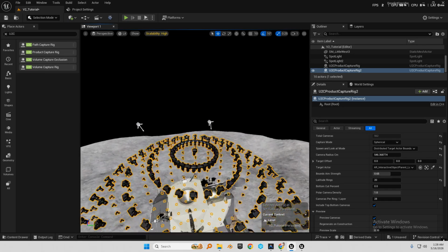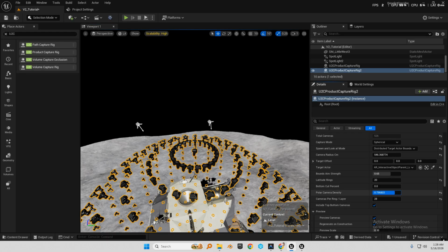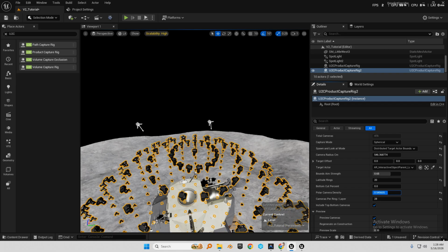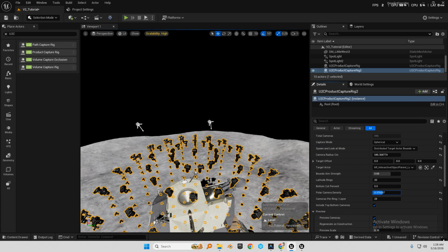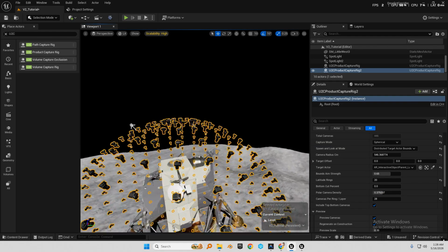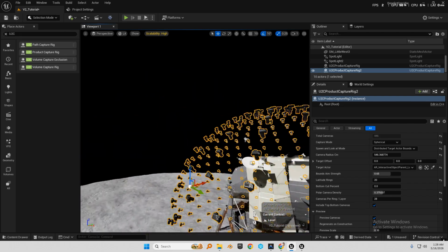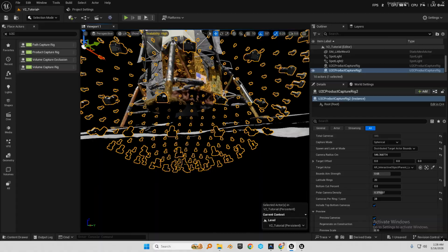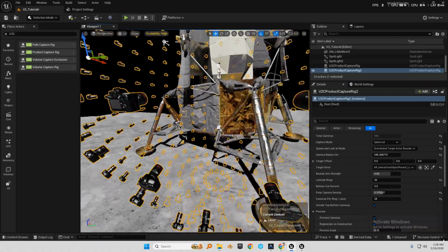So the way you can fix this is, there is a setting named polar camera density. If you reduce it, it reduces the number of cameras along the top layers of the sphere. So now you would notice even better camera distribution. Another problem with the sphere rig is, for example, if we go down, you will notice that a lot of cameras are spawned underground, which are not needed, right?